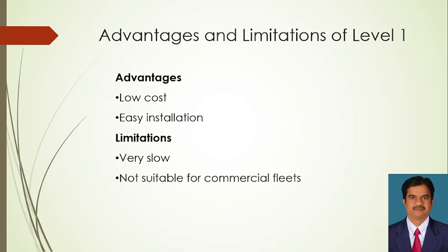Advantages of level 1 charging: it is low cost because we take the supply directly, whatever we are getting at home, and connect it to the vehicle to charge it, so automatically lesser cost and easy installation. There is not much procurement and investment in level 1 chargers, but the limitations need serious consideration. It is very slow because it takes almost 8 to 10 hours to completely charge the battery. So it is not suitable for commercial applications or commercial vehicles.